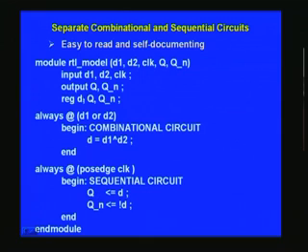Coming back to this, we have not said what a register is. You notice that the outputs in this always block are d, q and q underscore n. These are all registered values. That means it is basically a flip flop here. It is not really a flip flop in the usual sense of a sequential circuit, but still it memorizes that event, because whenever there is a change only then we take action. So some sort of storing is taking place there.